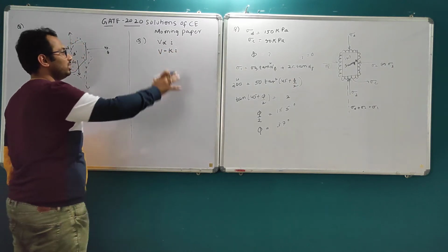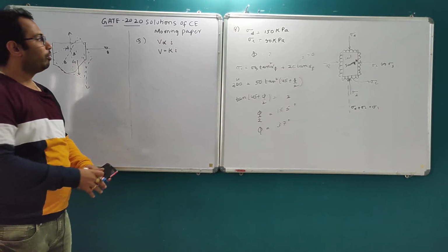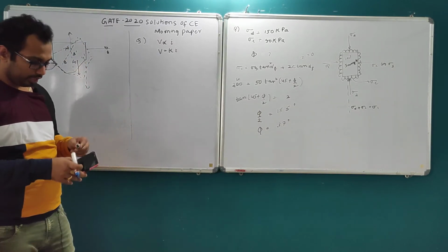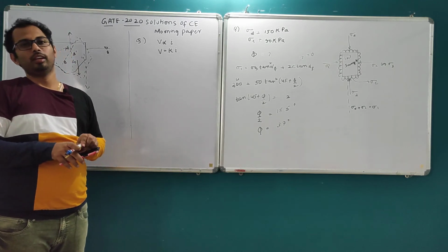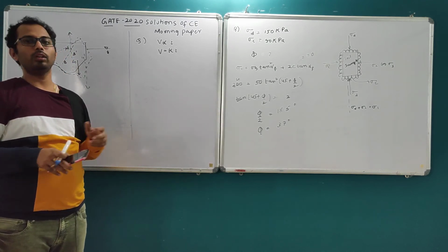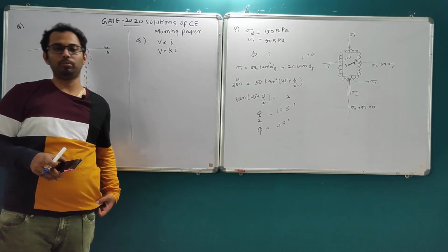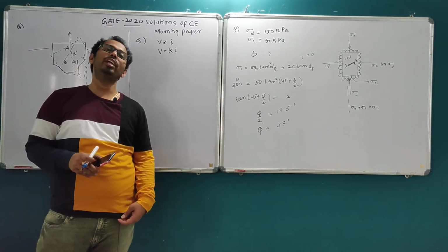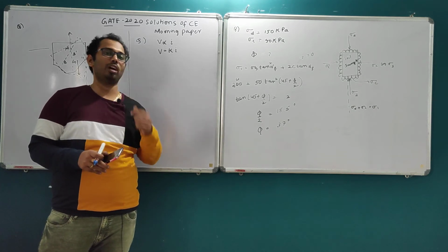But there are some assumptions to keep in mind before deriving this equation, so we apply Darcy's law in soils. In soil, the velocity of water will be very negligible, right? So the water cannot have any turbulence inside the soil strata.